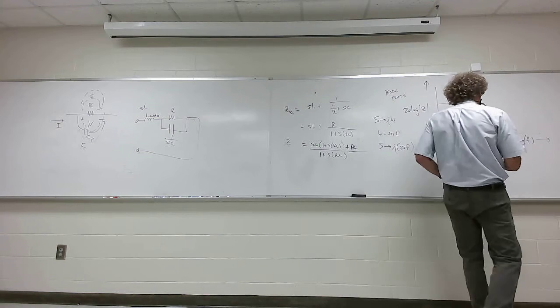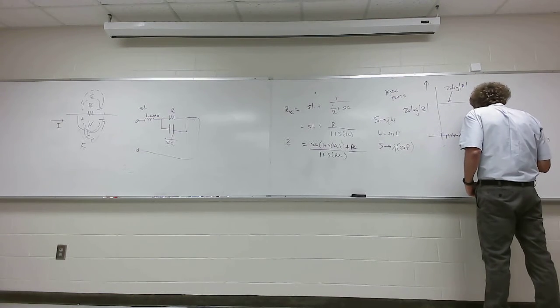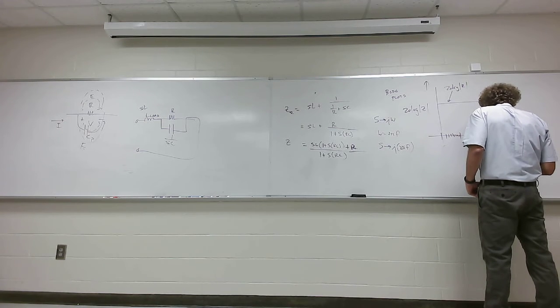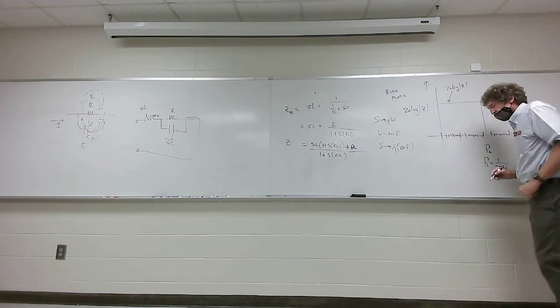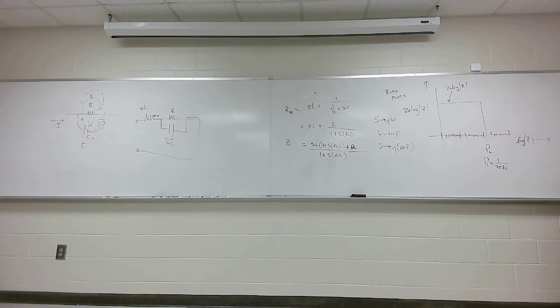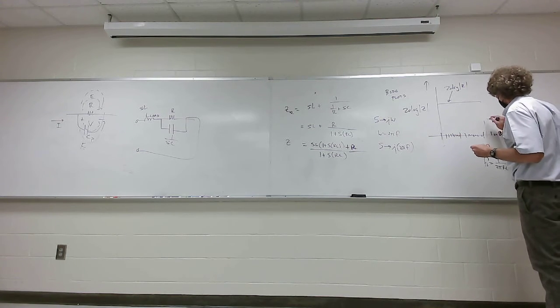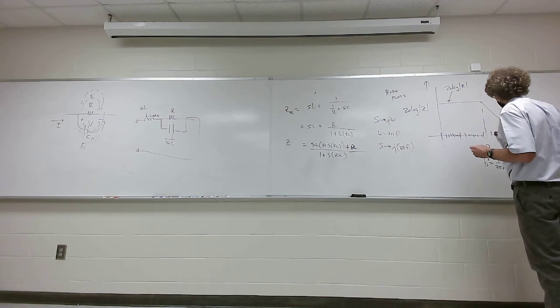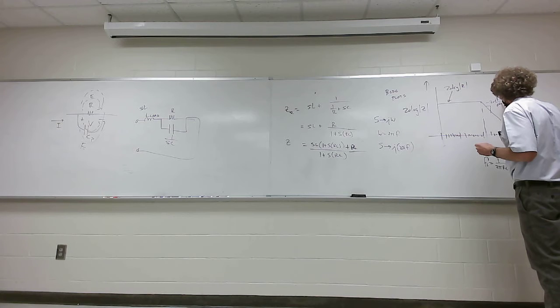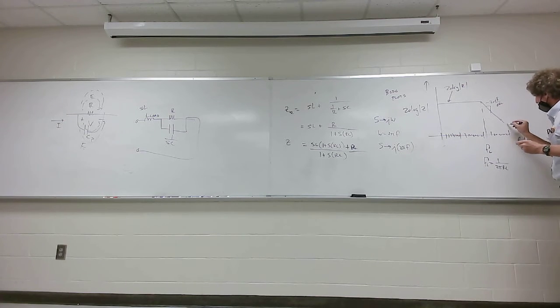There's going to come the first frequency, I call it FL here, and FL is the low frequency cutoff frequency, and that's equal to 1 over 2 pi R times C. So this would be the first pole, and it'll start coming down right here at 20 dB per decade. I'll go over this a little more in detail in a second. Y'all follow me on that?